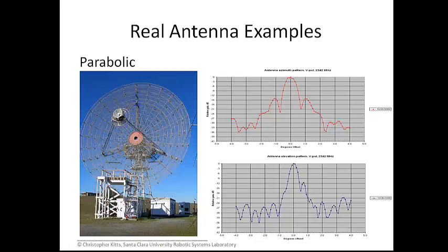And that ties into the negative effects that I want to talk about in terms of gain. It's wonderful to have a very high gain antenna. It really focuses your power. For the same power, you can broadcast over more range, or at the same range, you can have a successful link for less power. So those are really two excellent ways of exploiting the idea of high gain.